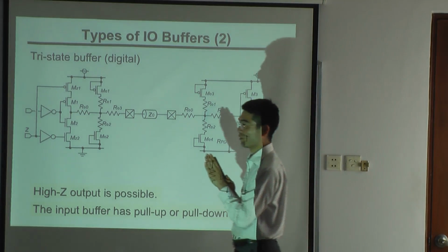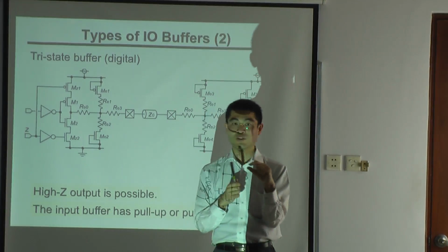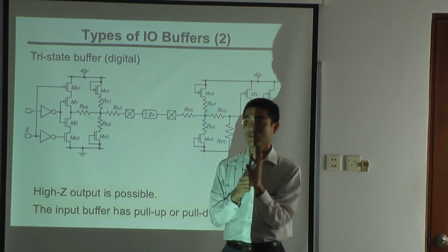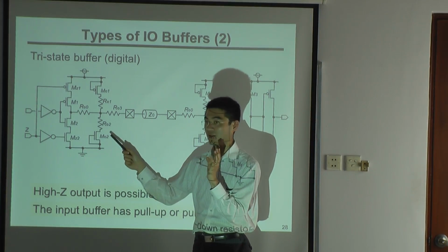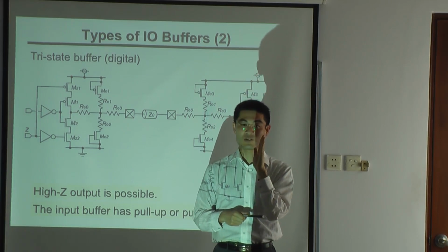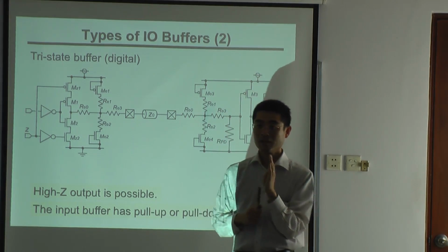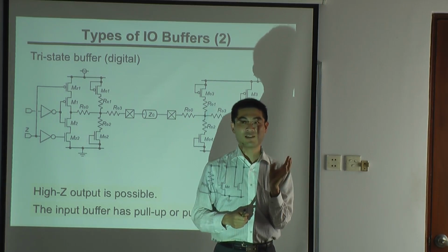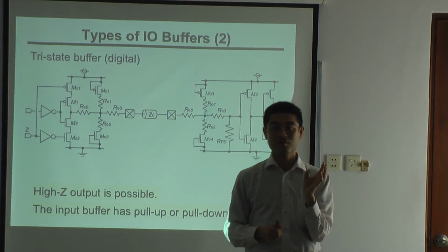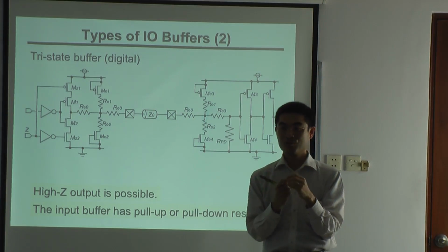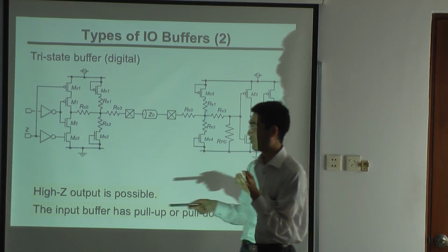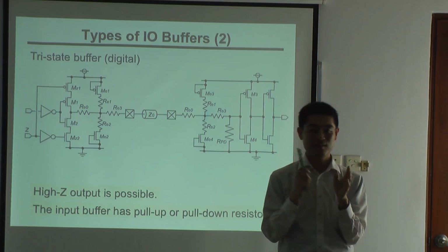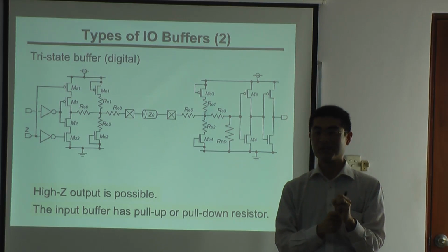So sometimes power amplifiers put in intentional circuits to adjust the resonance frequency. You can utilize the ESD protection circuit as the adjusting C. And if the ESD protection circuit C is much larger than your desired capacitance, you have to reduce it, or you cannot put in the ESD protection.